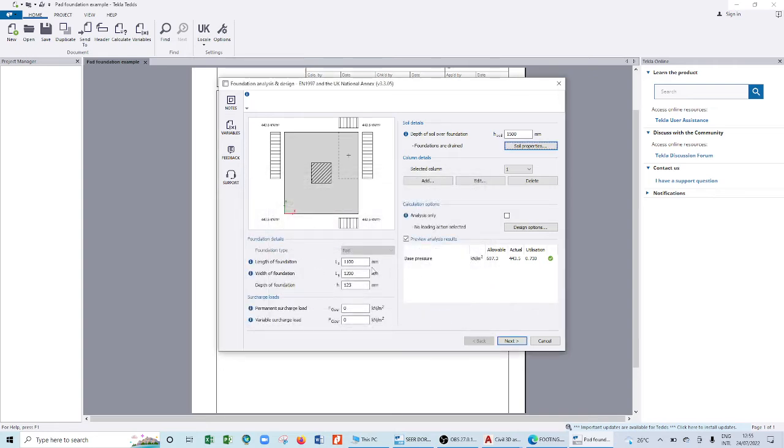So when you press OK, remember our size of footing was 1,200. If you leave it at 1,200, the way you have left it, when you design, remember, number 1, you design for safety, number 2, you design for economy, but we call safety paramount. So meaning, much as I'm designing, I don't need to over design. So you can check from here whether you have over designed the footing.